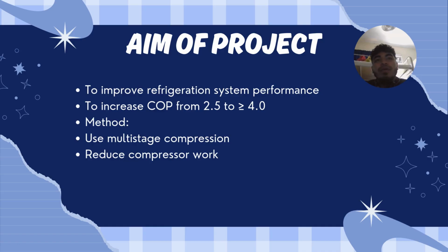So the aim of our project is to improve the performance of the refrigeration system. Our main objective is to increase the COP from 2.5 to at least 4.0. This is achieved by reducing compressor work using multi-stage compression.